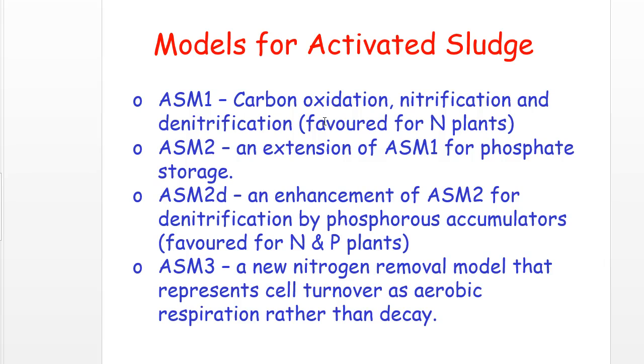Then this was extended to ASM2 by also including phosphate storage, or biological phosphorus removal. And then, as new discoveries were made regarding these reactions, modified versions of these two have been introduced, and ASM2D is probably the most popular at the moment.